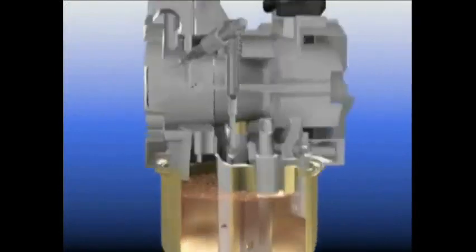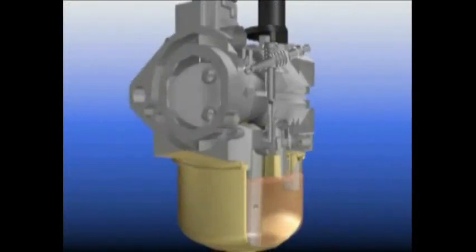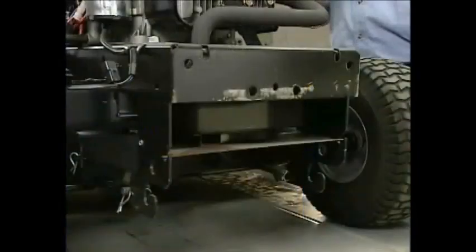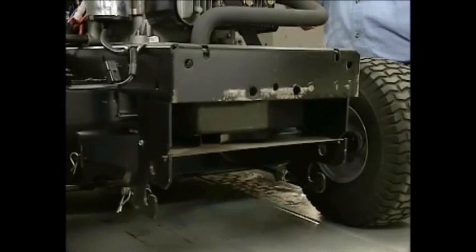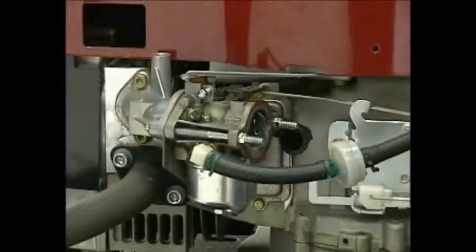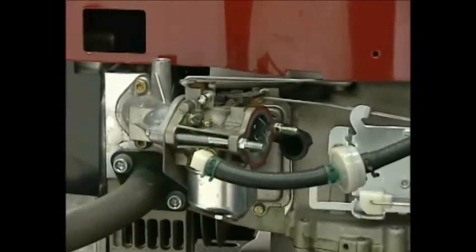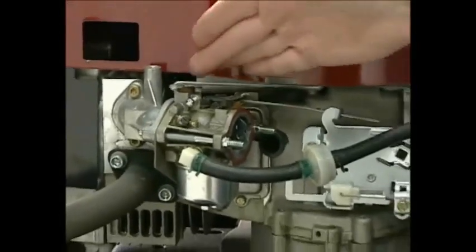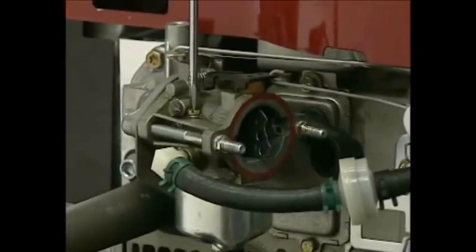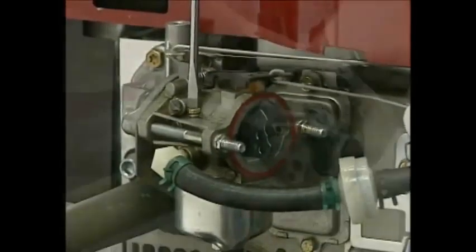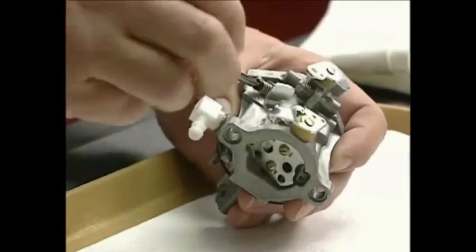Then, as the engine begins to coast down, the governor spring opens the throttle plate. This is a normal function for the governor spring. As the governor spring opens the throttle plate, the low pressure area moves above the main nozzle. This causes a shot of fresh fuel to enter the carburetor and engine speed increases. The result is hunting and surging. To override the governor, simply hold the throttle plate closed to force the engine to idle. If the engine continues to run, you know there's a problem with the governor system, and you would need to troubleshoot the governor. If the engine stalls, you need to inspect the fuel supply route to the idle circuit.